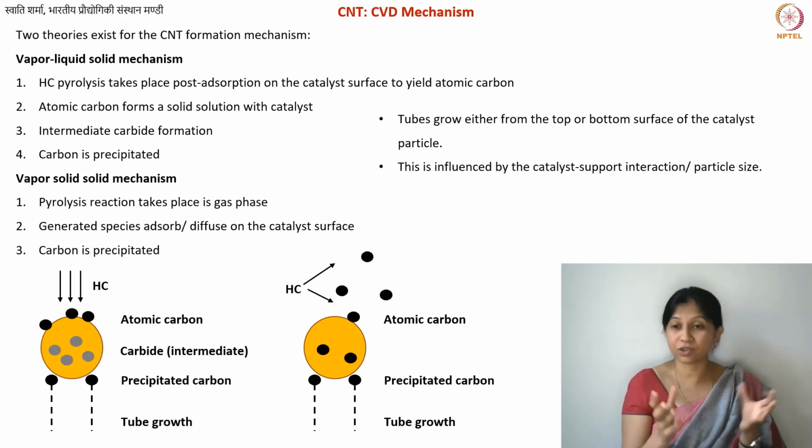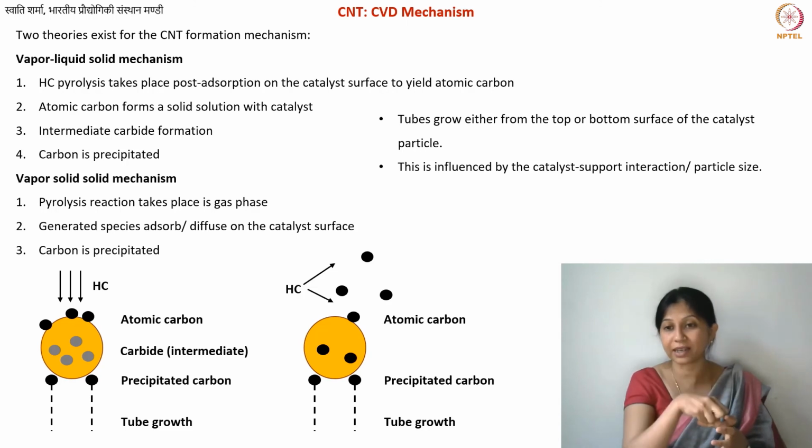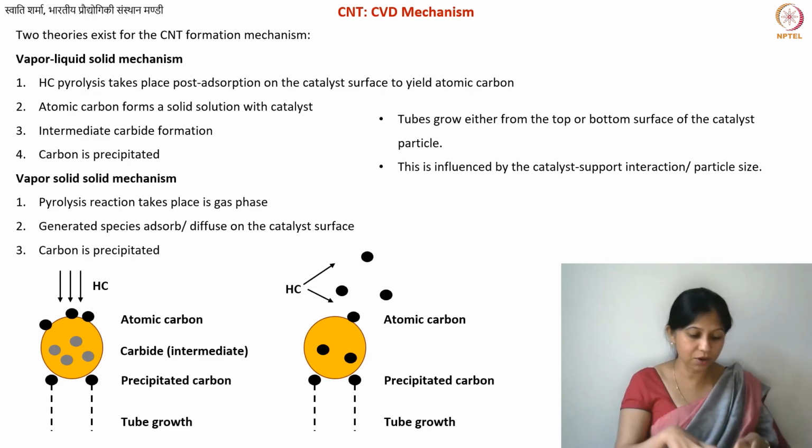Although very large particles you will not have in the case of carbon nanotubes, still, within the range of the particles, whether you are on the lower side or on the higher side, something that strongly influences this process is whether you have a very good adhesion of your catalyst with your substrate.